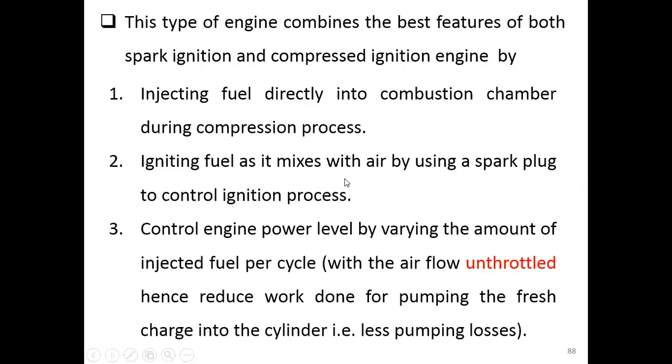We do not rely on the temperature of the air, which can vary from time to time. We intend to ignite it ourselves by using the spark plug. We are the ones to determine the spark or the ignition. This is the good part of the SI engine. We control the engine power by varying the amount of injected fuel per cycle.